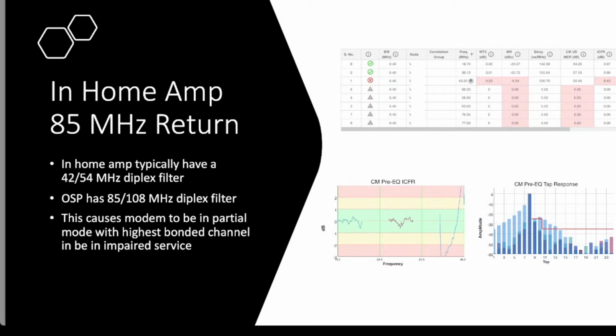On the right-hand side, we see the pre-equalizer tap chart. Most of the digital tap charts are pretty happy, except we see one has a lot of, as we talked about before, group delay. We see that group delay because, as John mentioned, all the taps to the left of the main tap number 8, or digital tap number 8, are severely elevated.